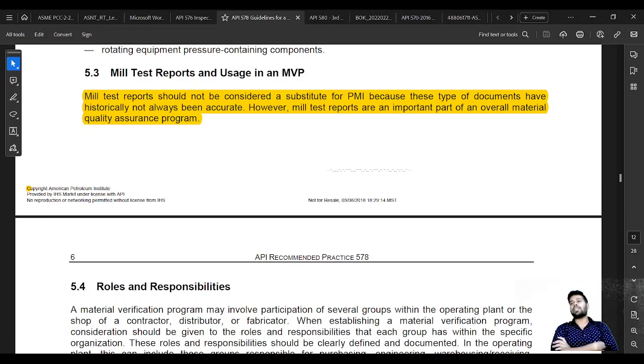So this code tells us that you have to have a material test certificate. There is no doubt about this. But you would also have to do some experiments or testing so that you can understand that whatever material you are getting is as per the requirement. When you correlate this result with the MTC, it should be the same. If your testing gives you different results and the MTC gives you different results, then there is a high chance that material has been substituted.